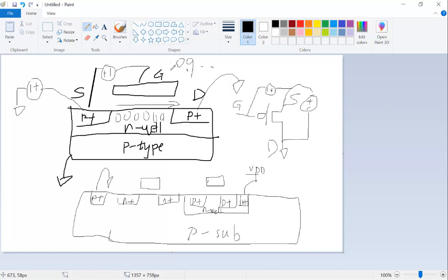So you have a wafer here, and then dope the well, then dope the P plus, okay, and then have another layer here, and leave a via. So the via is a hole that can hold metal. Like PCBs have different layers. You can run metal traces to the top, and then on the top layer you can have the metal traces running, so you can make the connection, right, to the metal 1, and you have another silicon oxide layer to insulate the different layers.